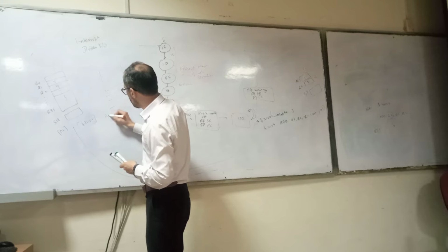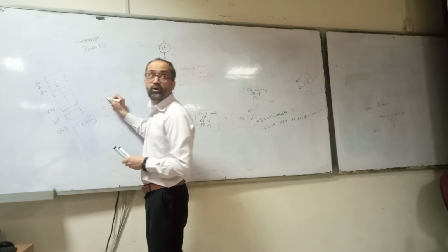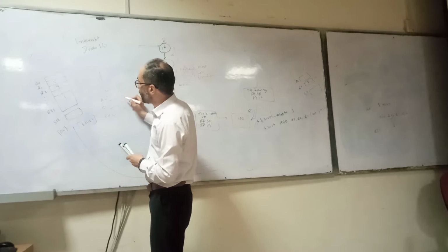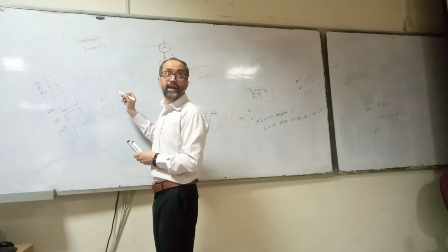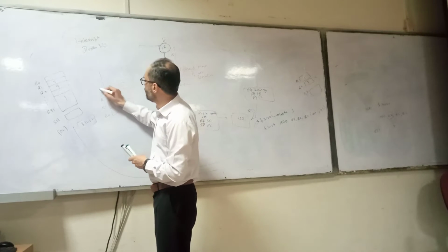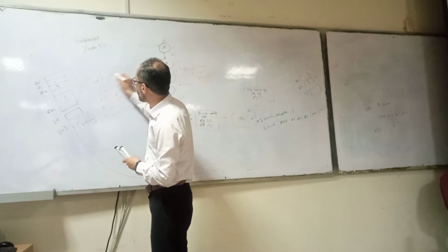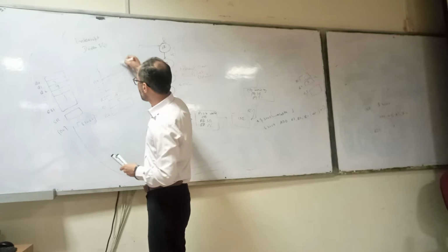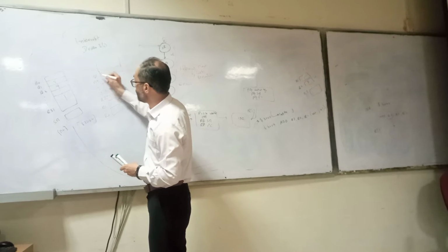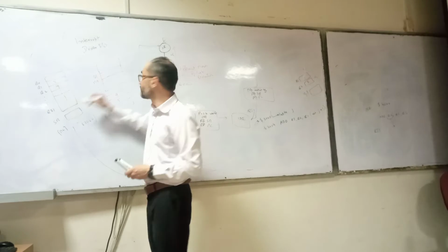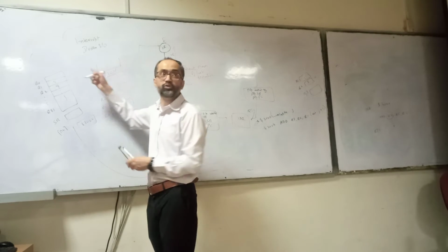So it pushes R0, then it pushes R1, then it pushes R2. So what is the value of R1? 5. Then 9. Then R9 is also pushed on the stack. On top of that we have SR, the status register. So maybe the status register NZCV, these are the flags. NZCV, these flag values. Okay?